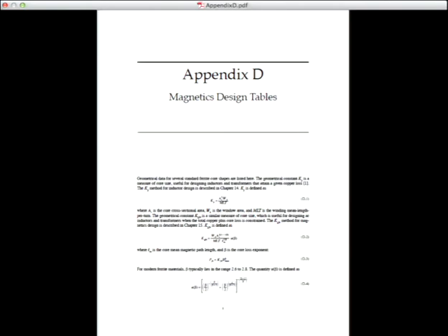We're going to talk about what KG and KGFE are today and in upcoming lectures. They don't really apply to this homework set, but those are a measure of how magnetically large a core is as far as geometry goes, which we will use to design inductors and transformers.